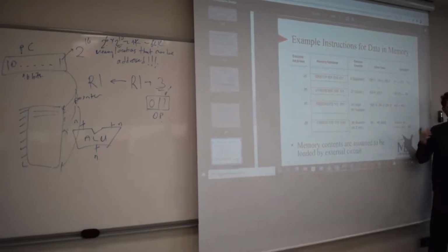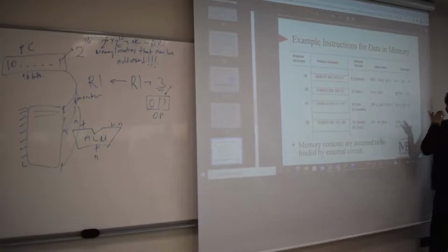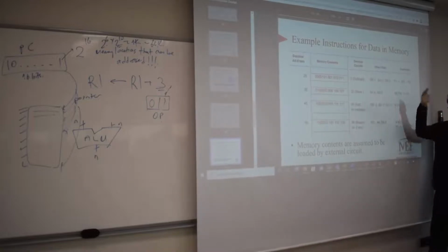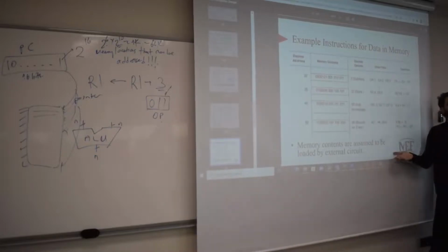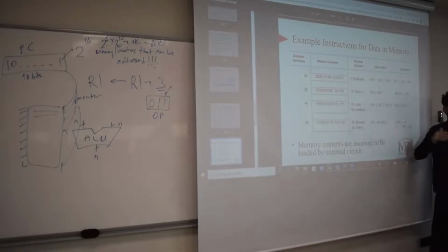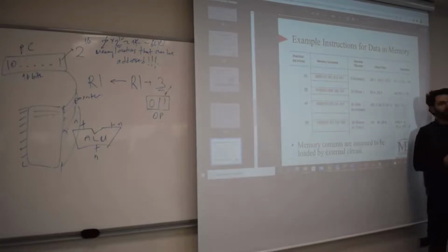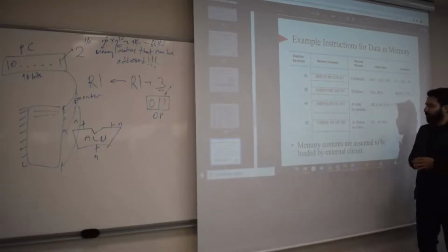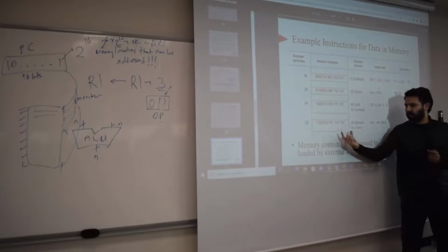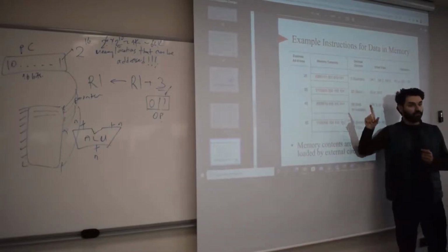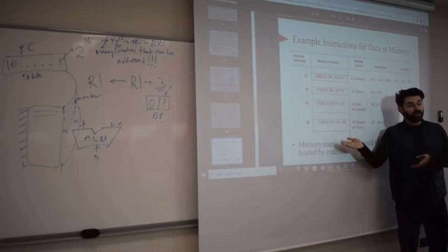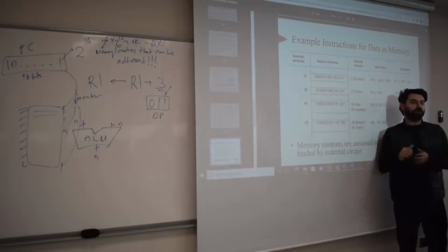So you also have to check this in your hardware. But checking this is pretty easy with an AND gate, right? Just put an AND gate. If that is 1 and this condition is satisfied, right? If it is 0, then the AND gate will always output a 0, so that will disable the rest of the hardware, right? So checking something is pretty easy in hardware by just putting an AND gate. Okay, anyway, so this branch on 0 is determined by this opcode, and these are interpreted the way that I just described in the format. That's why the format is important, because without the format, you would not be able to interpret these bits.